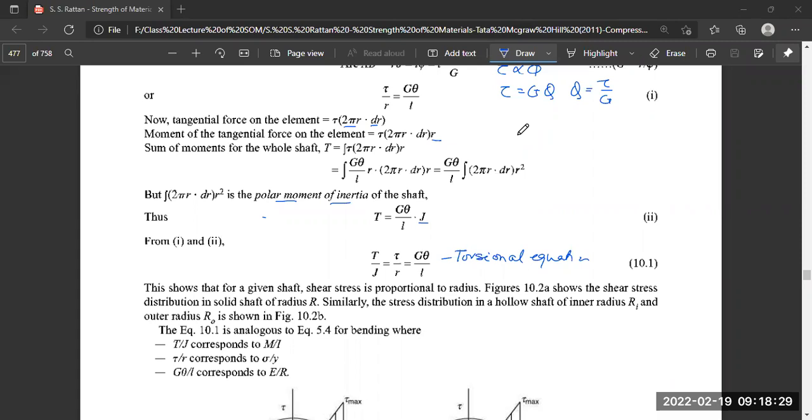We are supposed to investigate how this affects our bar from our subject point of view. That means we are supposed to investigate the shear stresses, the resisting forces, created in the bar due to this torque. We found that shear forces act over each cross-section of the bar. This shear stress may be zero at the center of the bar, and maximum at the outer radius of the bar.